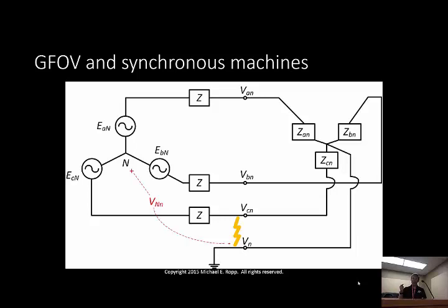If I fault phase C to ground, you see VCN, got the little lightning bolt down there to the neutral. Now what happens is I've got a voltage VNN. The voltage between that middle point and true ground is ECN. It's the back EMF that's produced on that phase. So that's what's happening here, that the N point is not ground referenced, and it gets pushed out into the middle of the triangle by the fact that these voltages, the phase-to-phase voltage relationships, are being enforced by the generator.